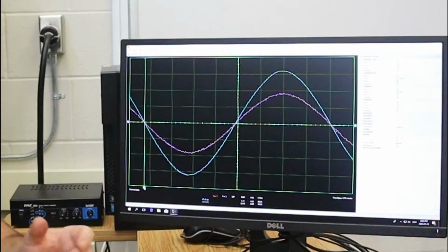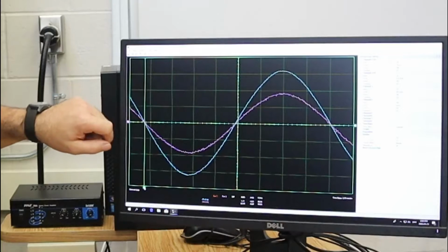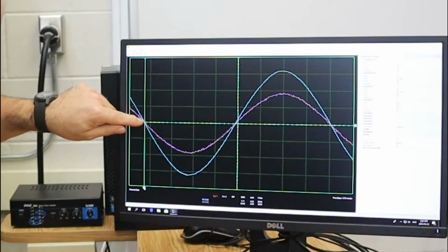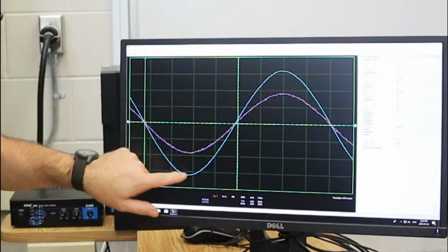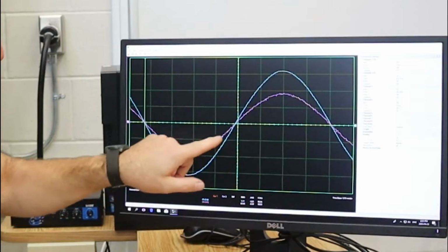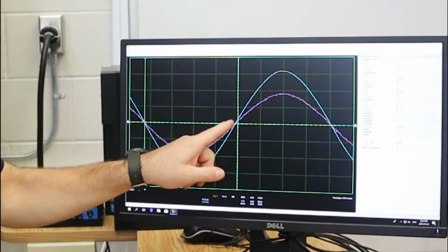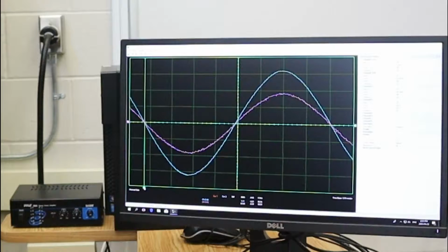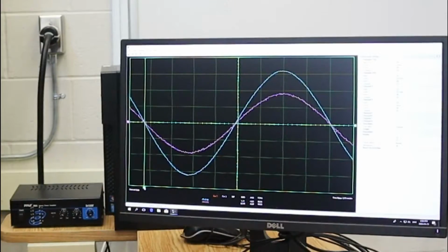According to our text, voltage and current are supposed to be in phase. And what they mean by that is that right at this point, when we're going into the negative alternation, the voltage and current waveforms have no phase angle difference. They start at the exact same point. They rise in unison, they both peak in unison, and then they collapse in unison. They cross over the center line of 0, because this is time base, and then they rise again in unison, peak, and collapse in complete unison. So this is what they mean by zero phase angle difference.